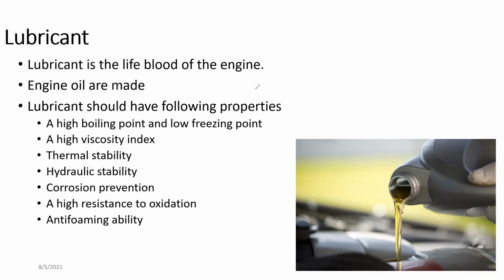The engine bay works at over 500 degrees Celsius, so at that temperature, if the lubricant is not thermally stable, it may end up creating unwanted contaminants inside the engine. Hydraulic stability: it should be able to flow at all temperatures.